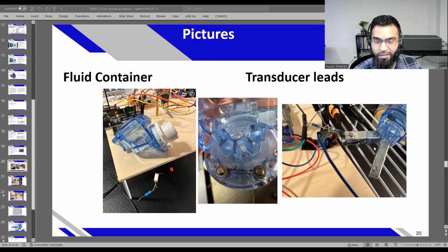I don't want to solder directly onto it, and it's kind of an awkward thing to have an alligator clip. So these spring clips work well. You can solder to a lot of different items. You just have to sand it first, and then you can solder to it. It's easy enough. It's a little bit messy, I'll say, but I'll explain each part.